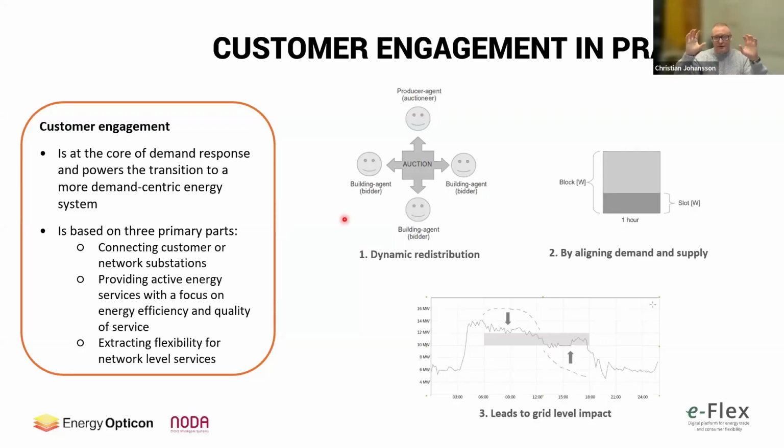The aggregate optimization system wants to control maybe 5 megawatts, but one individual building can't absorb 5 megawatts. So it has to distribute 20 kilowatts over there, 50 kilowatts over there, and so on, until you have your 5 megawatts. And this is done continuously by this auction process. So all the buildings are bidding and trying to buy control actions.